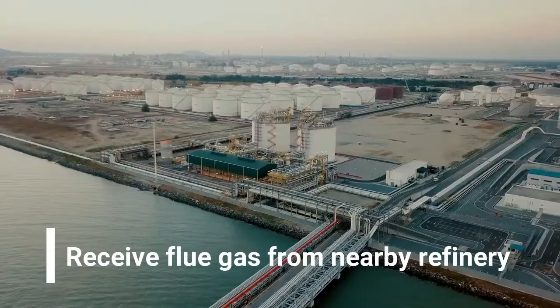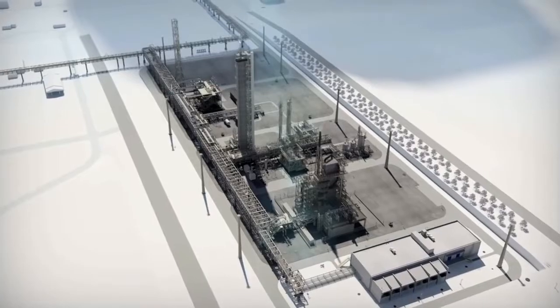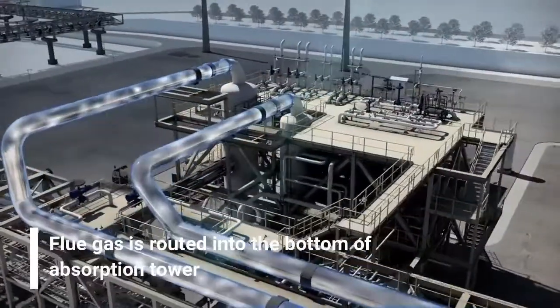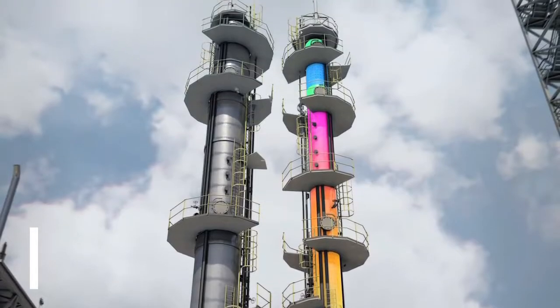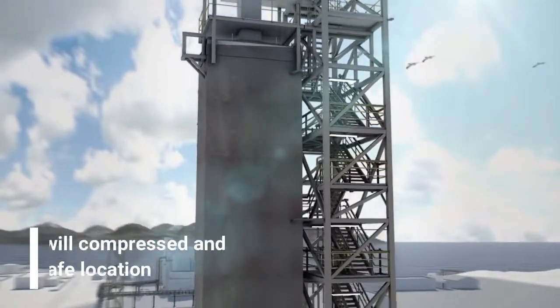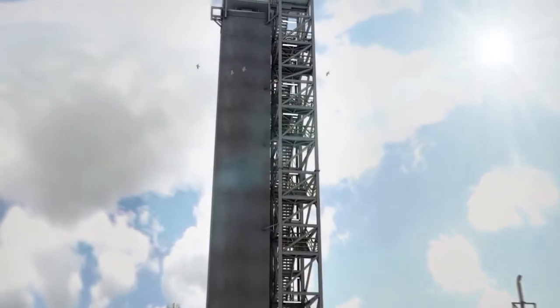In this process, the center will receive the flue gas from the nearby refinery. This process is utilized when the flue gas containing CO2 gases gets direct contact with amine. The flue gas from a gas power plant is routed into the bottom of the absorber tower. The flue gas flows upwards and meets a liquid containing water and amine that will absorb the carbon dioxide gases from the flue gas. The captured carbon dioxide will be compressed and transported to a safe location.